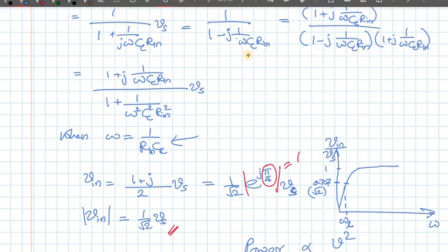In fact, if you increase the frequency further and further, the parasitic capacitance or leakage capacitance between the terminals of the transistor will also become significant. The impedance due to them will be small enough that there will be leakage current, and some current will not flow into the transistor itself, so we will not get the required gain.